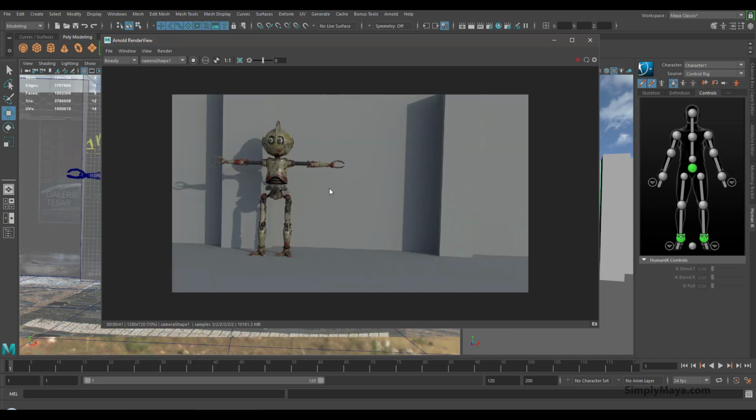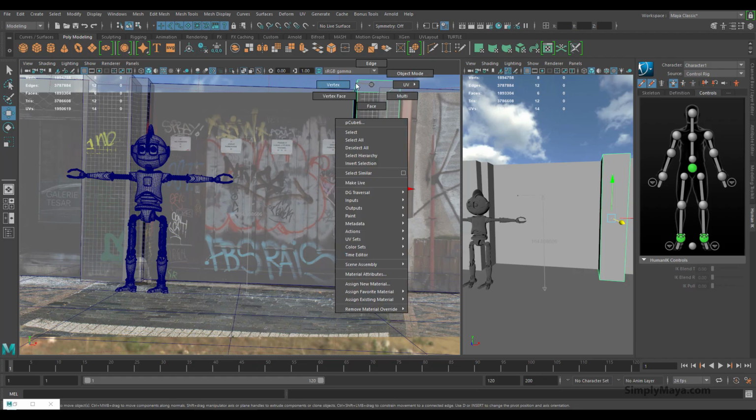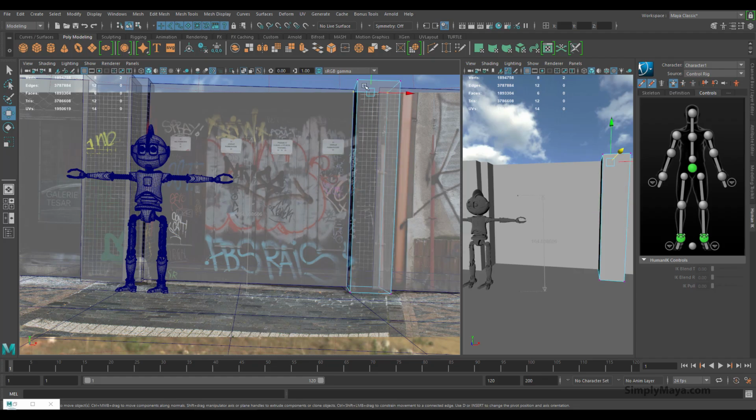Okay, so I've got a fairly low-res render here of our scene, and I can immediately see a problem with one of our shadows. It's cutting down diagonally here, which is going to look fairly weird, because if we look, this building would not obviously end here, it would extend upwards. So just to get us that shadow in the correct place, I'm going to select all the vertices on top of the wall here and extend the wall upwards so the shadow doesn't go through a cut-off point.